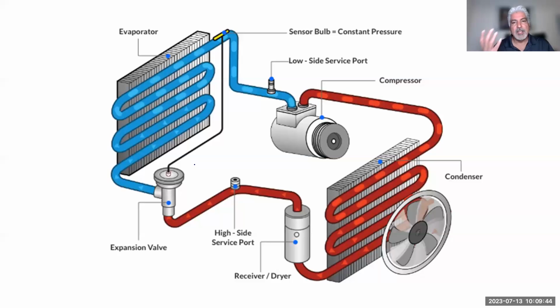So when I see compressors that are installed and the clutch goes out within 6 months or 3 months of operation, a lot of people say, well, it was a defective compressor. Maybe, but it could also be that we had inadequate voltage going to the compressor. So we have to take a meter and measure the voltage drop across that compressor clutch connector. You have to do it at the compressor clutch to ensure you don't have any unwanted resistance either in the relay or the wiring going towards the compressor.